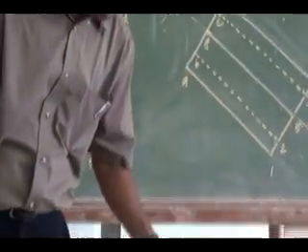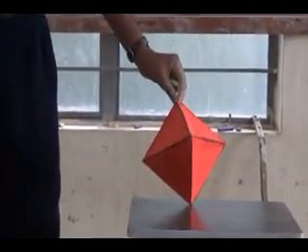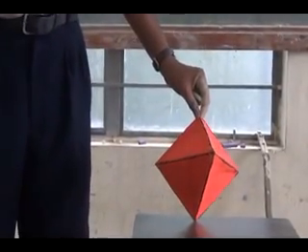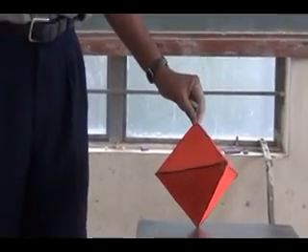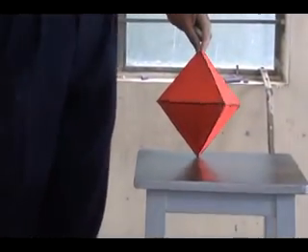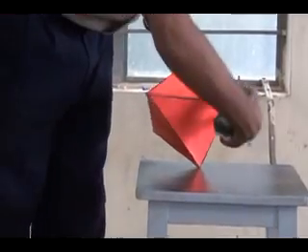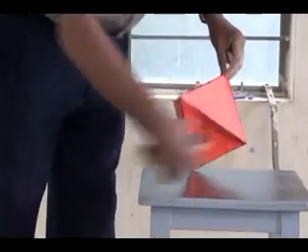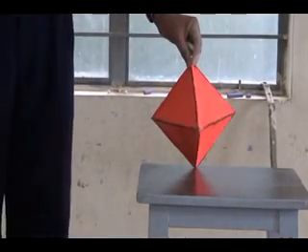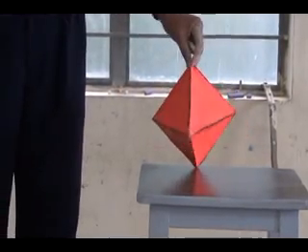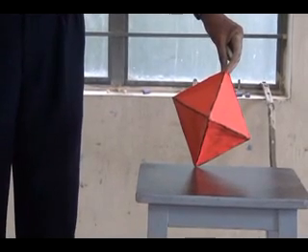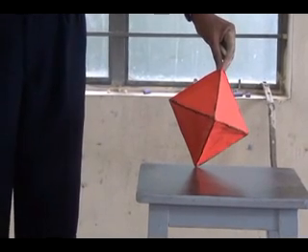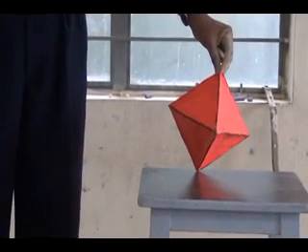The base edge adjacent to the resting corner is 20° inclined to HP. In this orientation it is equally inclined at 45°, so one of the edges I am inclining as 20°. So this is about the base edge and the resting orientation.